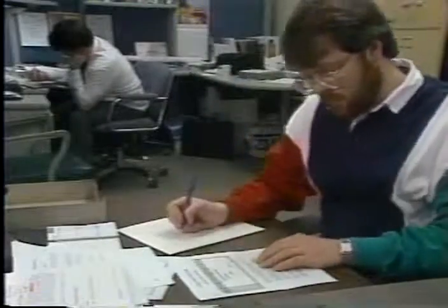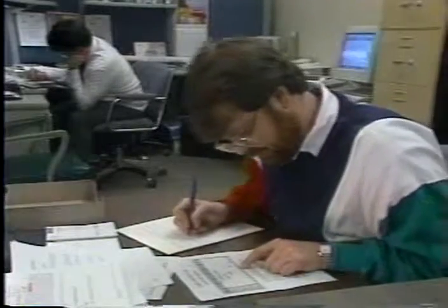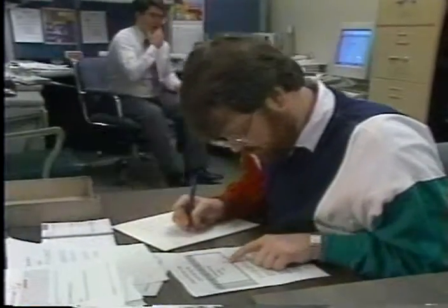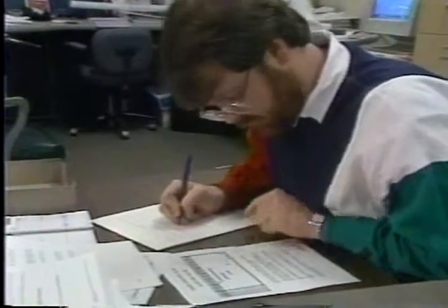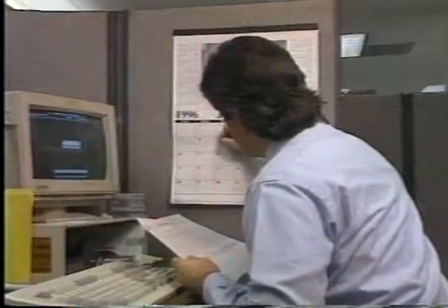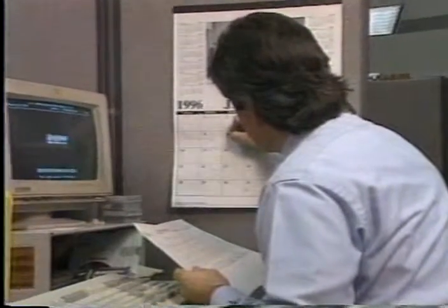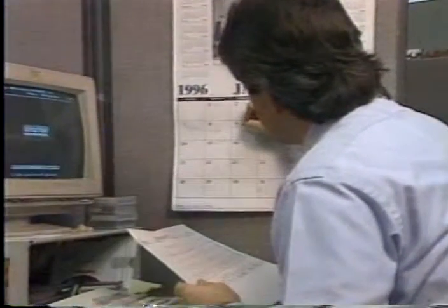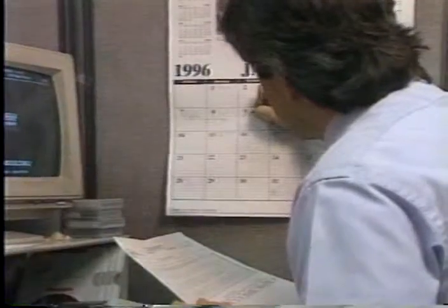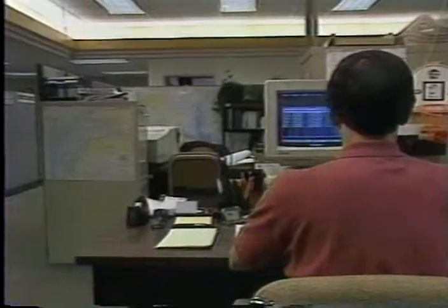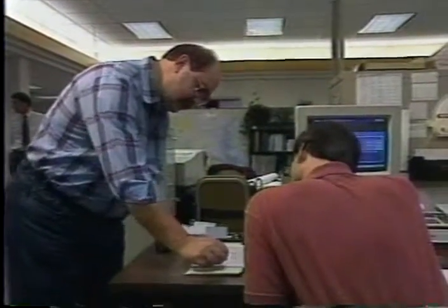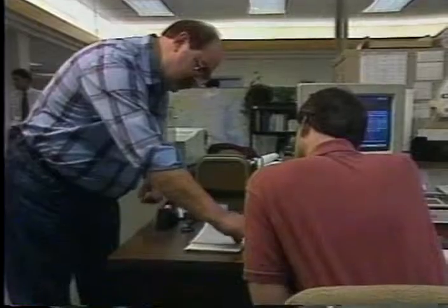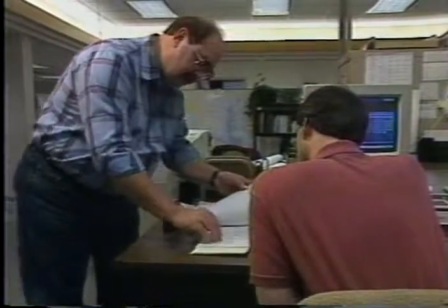There are several manpower distribution methods: equal distribution, prorating, and engineering judgment. Equal distribution distributes manpower equally to each time period. The proration method recognizes the variance in the number of days that are actually available for construction work in the time period.